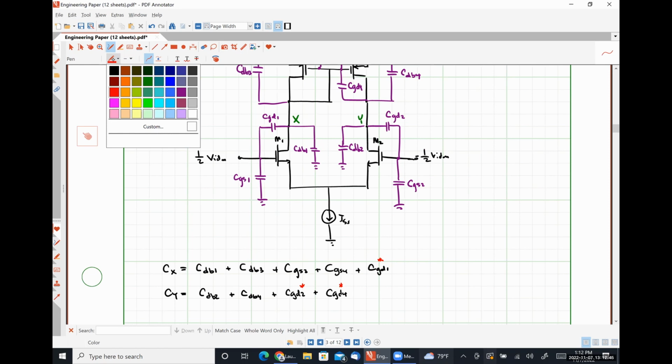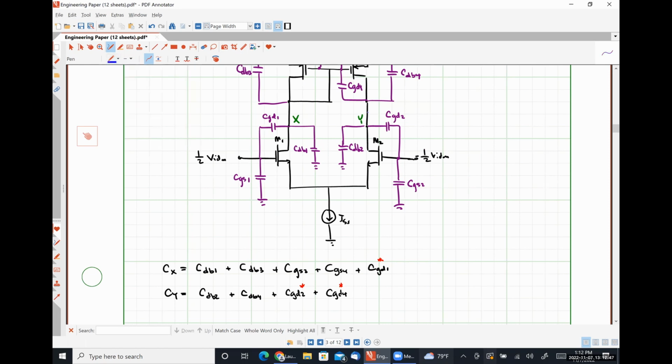And I'm going to do something else here really quickly. I mentioned this the other day, that our single stage op amp is effectively only capable of driving capacitive loads. So let's consider what happens if we also have some capacitive load connected to our device. So I'm going to put plus CL here as well. We'll talk about why that's important in a few minutes.